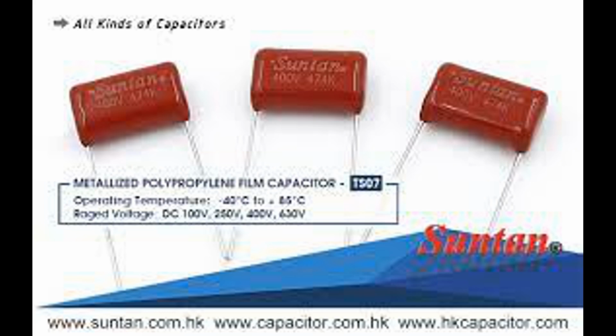2. Capacitance. The ability of a capacitor to store electrical energy is determined by its capacitance, C, which depends on three factors. Surface area, A, of the electrodes. The larger the electrode's surface area, the more charge can be stored. Distance, d, between the electrodes. The closer the electrodes, the stronger the electric field and higher the capacitance. Dielectric constant, epsilon, of the plastic film. This is a property of the dielectric material that describes its ability to support the electric field.